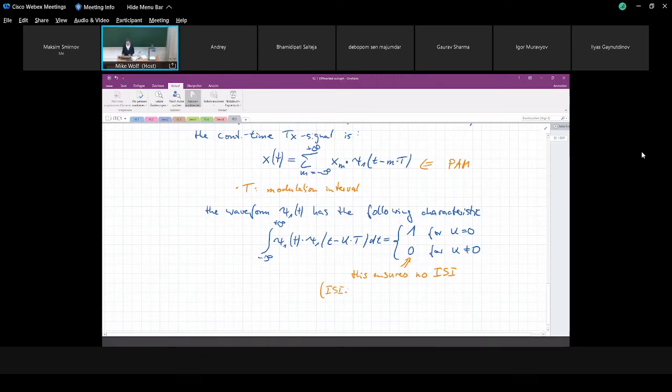This means that adjacent symbols at the receiver, at the output of our optimal detector, are statistically independent. So this is still a memoryless channel. There is no interference between symbols at the receiver. But we discussed this in communication engineering.